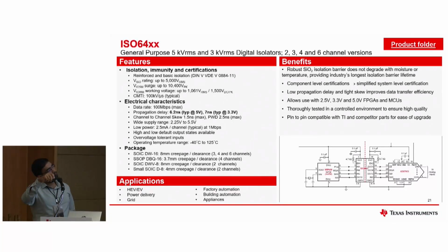So if you switch off this supply, now with over voltage tolerant inputs, you can have the 5 volt or 3 volt or whatever voltage domain that you're operating in at these pins. Earlier it used to be a violation of absolute maximum, and the device used to get damaged. The internal ESD structures or diode structures were not made for that. But with this device, from the feedback that we have got from the customers and the field, we have implemented that feature, and it's absolutely working fine.